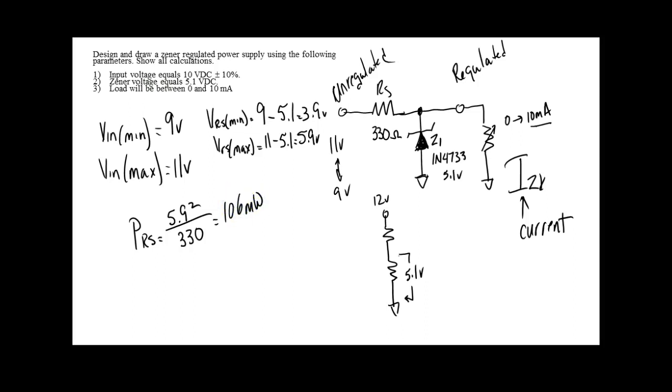So what size would we use? Probably need to double this and then use the next standard value. So if I double that, it's going to be 212. So we'd use a quarter watt. You understand that? Yes, no?